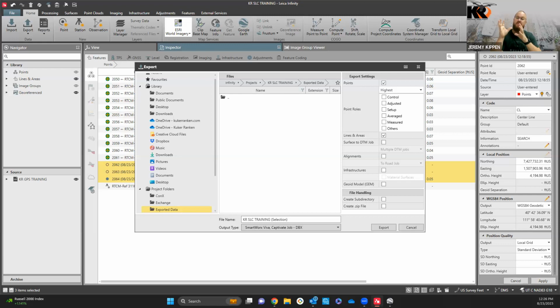So it is topoing, if you will. You are utilizing real-time positions to go along, and those images are geo-referenced to a northing and an easting. And with the processing on the data collector, you can select the image in the field. If you have any further questions, I can definitely walk you through that process. That was one of the greatest tools that actually came out for the field crew.